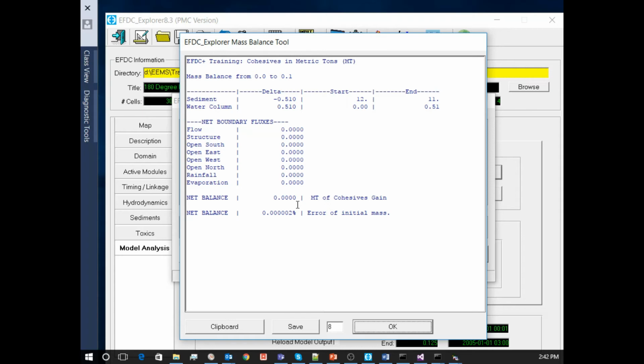If your flows are plus or minus 5%, and you say I'm going to use the measured data regardless, and you put it on a reservoir, you know the volume elevation relationship, you know your inflow, you know your outflow, you still have groundwater and evaporation as a different issue, but it's very likely that you're either going to be filling up the reservoir too fast or draining it too fast because of the imbalance.